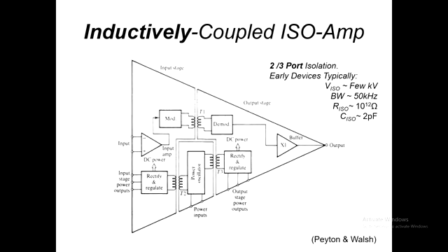So you'll appreciate that there can be a degree of interference from each of these power supply arrangements to the signal path. So we would need to make sure that either the frequencies are different, the bandwidths are different for power at input and power at output from the signal pathway, or maybe we could map them all orthogonally to each other so the magnetic fields are not going to be coupled as well.